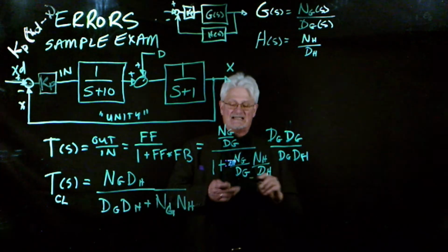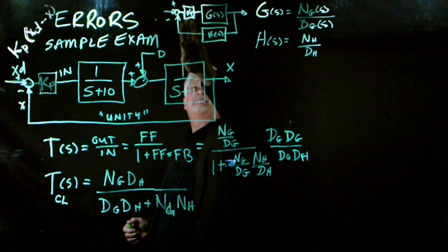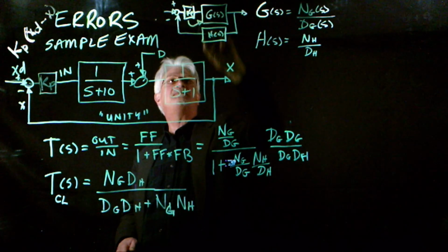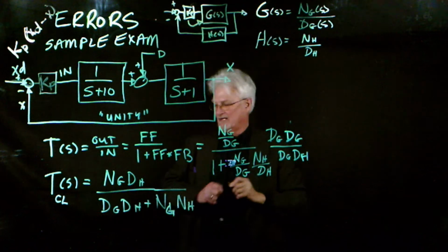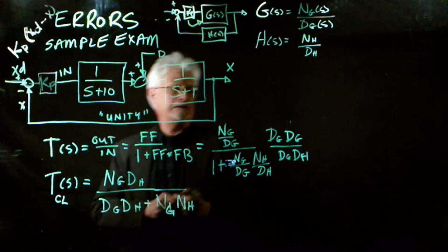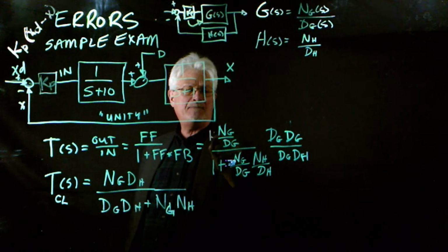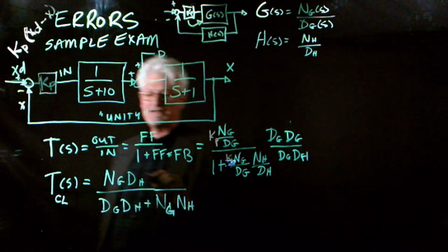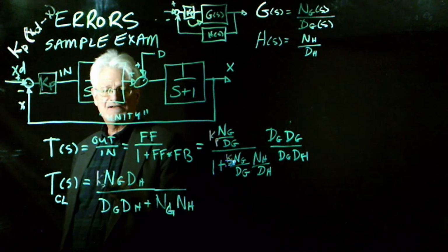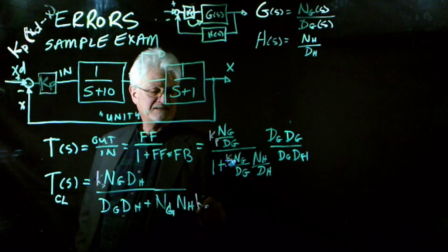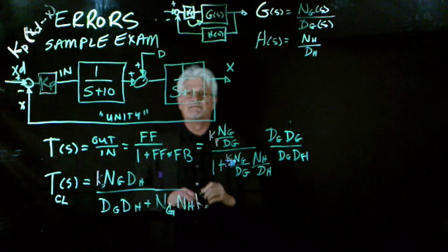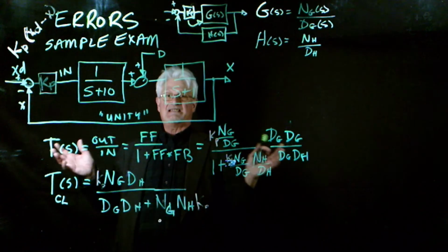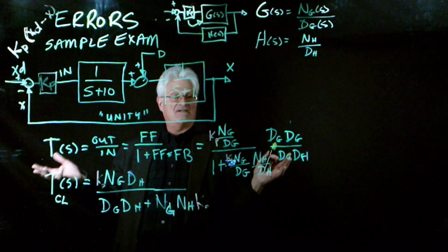Now, a lot of times, you'll see I kind of didn't put this kp in here, and sometimes people just absorb this kp into the g part. And so a lot of times they might say that's got a little bit of a kp on it here, and this has got a kp here. So sometimes they'll just add some of that stuff on there. And so what we can look at is what the steady state gain is for this. Right? So let's look at what the steady state gain is.